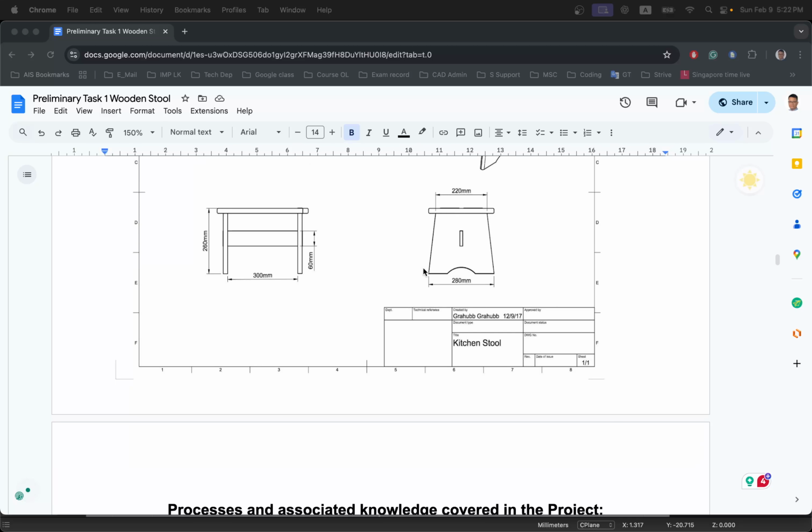By default, you should be using small objects millimeters, as shown in the material list. The convention is in millimeters. Always remember, once you open the small objects millimeters default template, your working grid is pretty small. So it's recommended to always go to file, look for settings, and change the grid to 2000 somewhere here, so you have enough space to work with. That is the first step. When it's done, you can go back to it for Windows Move.